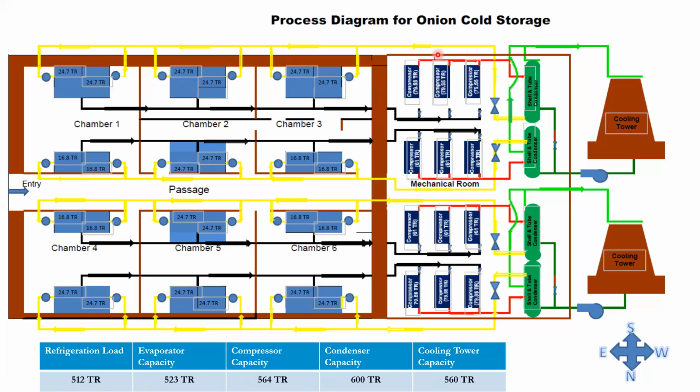If we explain one particular refrigeration system, from the compressor, this black line is the insulated line. This is coming from the evaporator. So this low pressure, low temperature vapor then comes to the compressor, and compresses to a required pressure. Then the red line, these are generally color coding, such color codings are used. Insulation lines are generally black insulations, so that's why black color is used. Then it compresses, then red color is used for the discharge line.